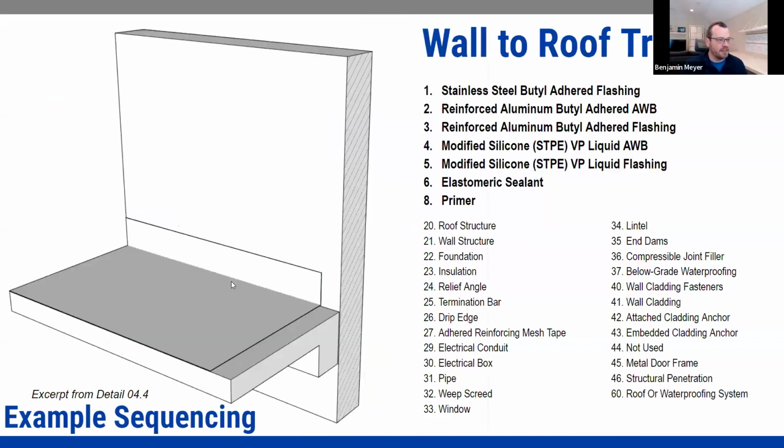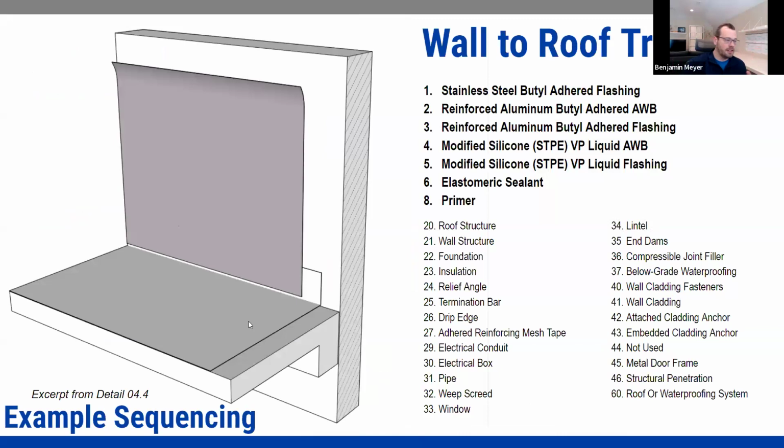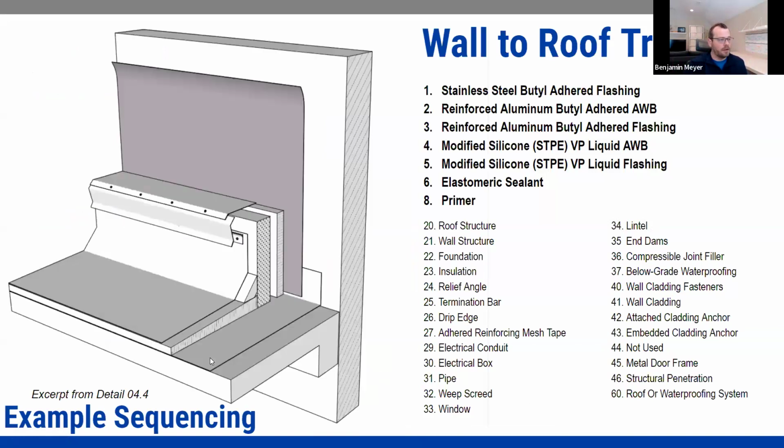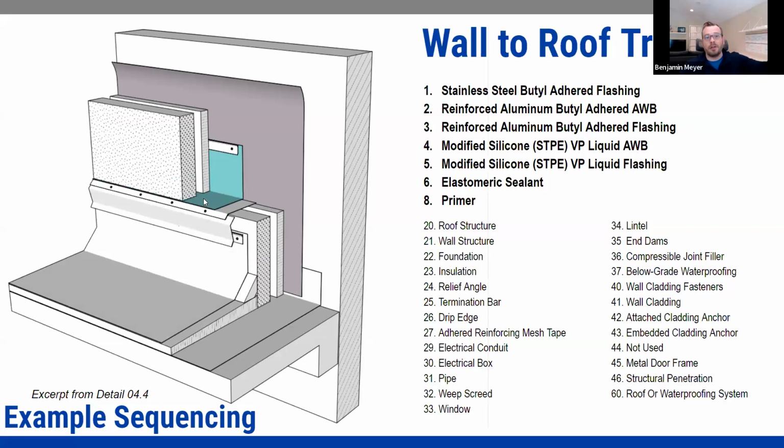All right. And again, from a sequencing perspective, starting from the bottom and working your way up is key. So with this one, we're looking at the roof side. In this scenario, they're both roof sides. So you have the vapor retarder, looking at that scenario where we have that air and vapor barrier on the roof side coming up and lapping over the vapor retarder from the roof. Then building your roof system, doing the through-wall flashing, which is a two-piece flashing, so you can get to that roof later on. And then treating it as a through wall where you put in your flashing, build your brick on top of that, and then go along up from there. So again, that transition is super critical. It is super hard to get right, and it's a lot of trades involved, as mentioned before.